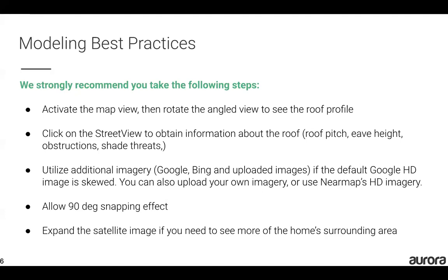It's really important to follow the 90-degree angle snapping effect. So once you place two nodes, or clicks, on the corners of the roof, you're going to have an orange dotted line guiding your cursor and automatically snapping it to make sure that you're drawing 90-degree angles. I would recommend following this for any traditional shaped home because it is going to have perfectly 90-degree angles around the